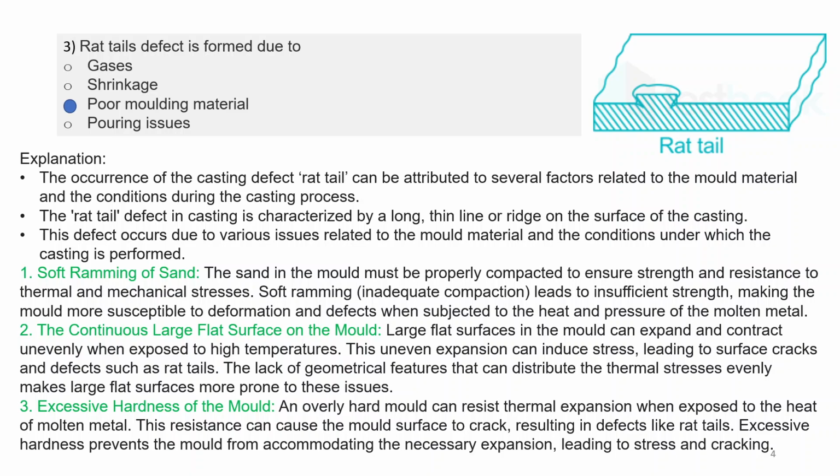Second is the continuous large flat surface on the mold. The large flat surfaces in the mold can expand and contract unevenly when exposed to high temperatures, and this uneven expansion can induce stress, leading to surface cracks and defects such as red tails. The lack of geometrical features that can distribute the thermal stresses evenly makes large flat surfaces more prone to these issues. Excessive hardness of the mold.